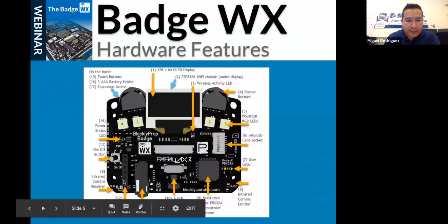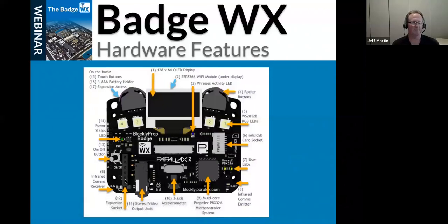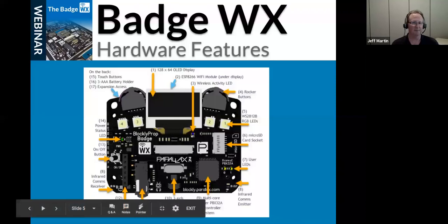So on this header here, Jeff, do you know what this one is for? The top and bottom pins of that header are actually the power connectors from the battery pack that slips in from the backside, positive and ground, right from the battery. And then the center pins, I know there are some I2C pins on there, so you can get access to the propeller's I2C bus. The one marked SW there is switch. I'm not sure if that's the power button or not. I will have to look that up. We do have documentation on this, and unfortunately I've never been privy to that particular.